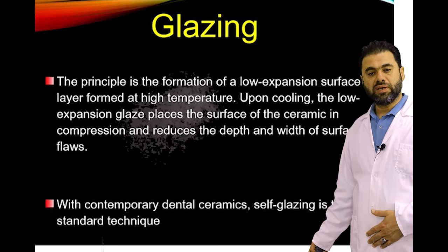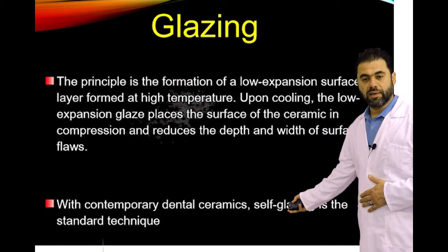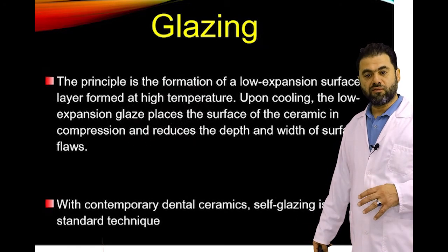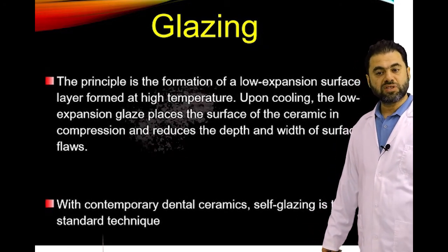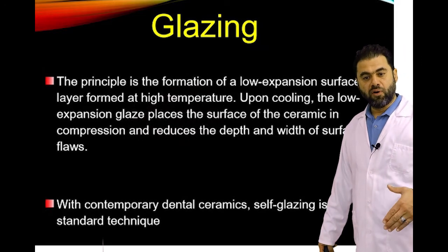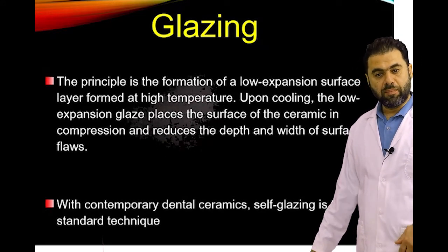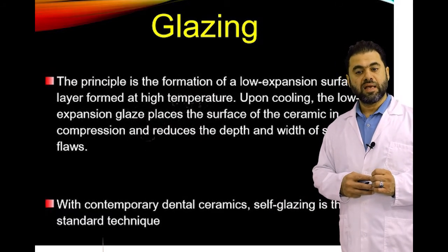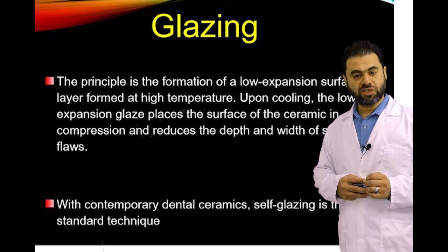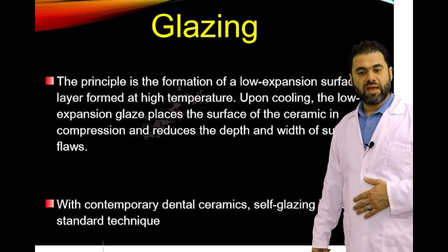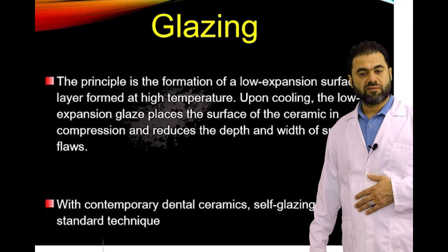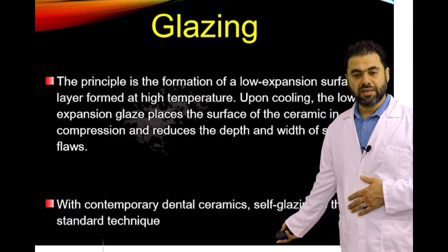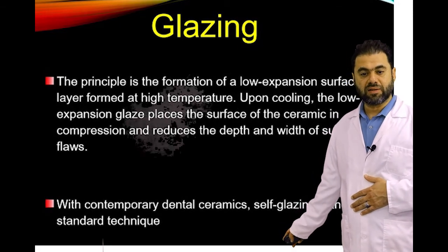The last thing we will talk about is glazing. The principle of glazing is the formation of a low expansion surface layer formed at high temperature. Upon cooling, the low expanding glaze phase puts the surface of the ceramic in compression and reduces the depth and width of the surface flaws. With contemporary dental ceramic, self-glazing is the standard technique.